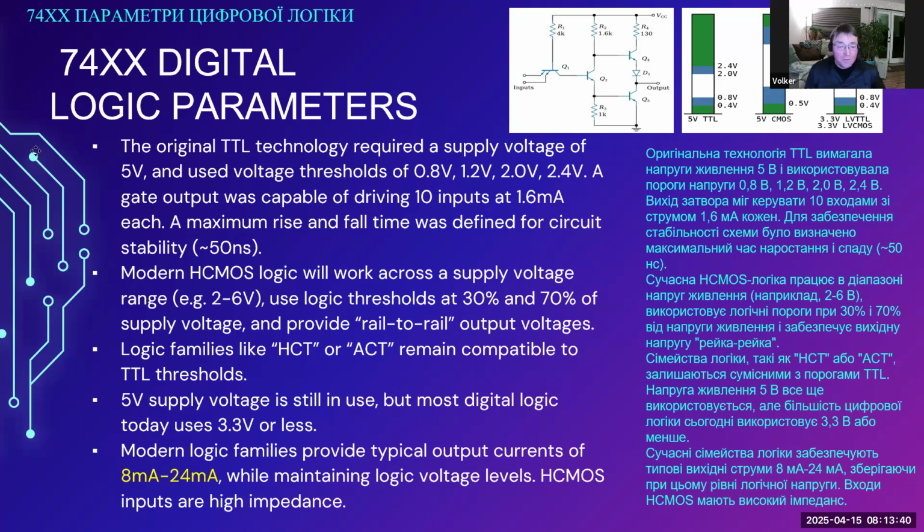So 5 volt supply voltage is still in use. It's also still in use for microcontrollers. The popular Arduino series of development boards use an Atmel AVR microcontroller, and that is a 5 volt type, for example. A lot of the Microchip PIC microcontrollers are still perfectly usable for 5 volt operation, but most professional commercial digital logic uses 3.3 volts, and pretty much all STM32 devices are 3.3 volt devices.